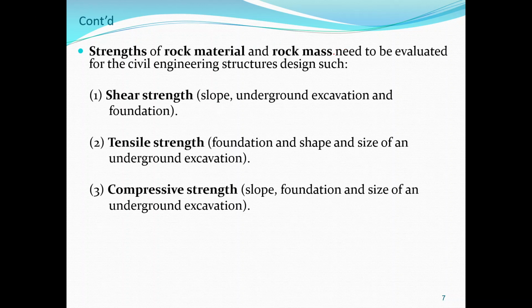The strength of rock is something we need to evaluate in civil engineering. Shear strength is used in slopes, underground excavations, or foundations. Tensile strength is used in foundations or underground excavations. Compressive strength parameters we use in slope design, foundation design, or underground excavation.